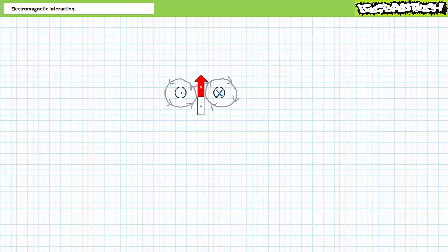Related to this phenomenon, the strength of the resultant magnetic field can be changed by varying the amount of current flow. In short, less current flow means less magnetism, and more current flow means more magnetism. Up to a certain point. We'll discuss saturation in later lectures. In summary, a loop of current-carrying wire will create an electromagnet, and the strength and polarity of the resultant magnetic field is capable of being controlled by altering the direction and magnitude of current flow through the loop. Lastly, unlike a permanent magnet, one can turn an electromagnet off by halting current flow.